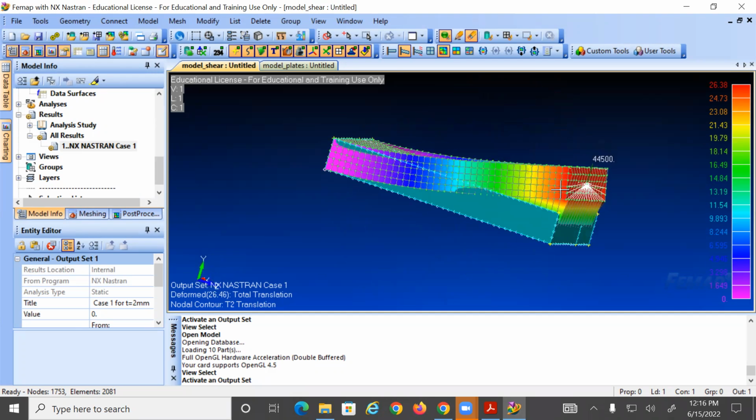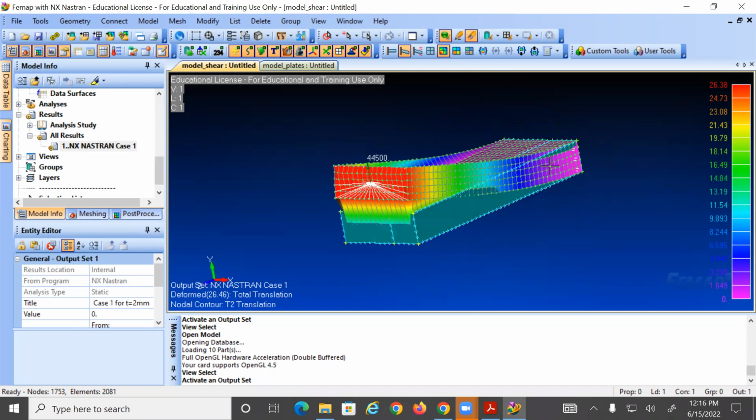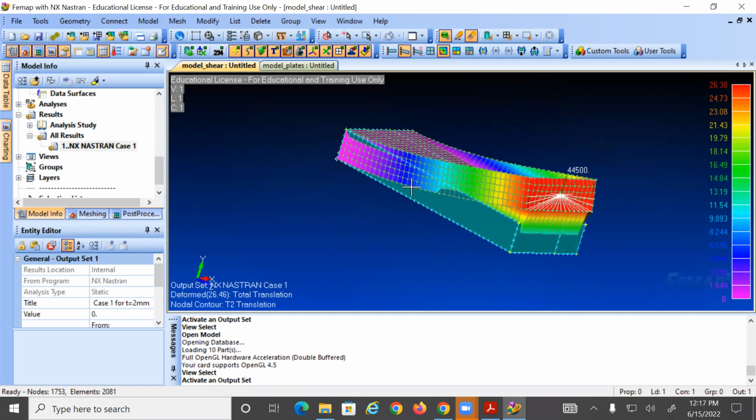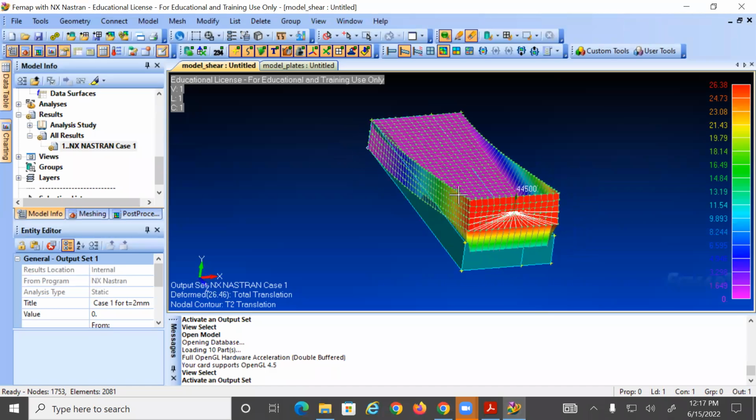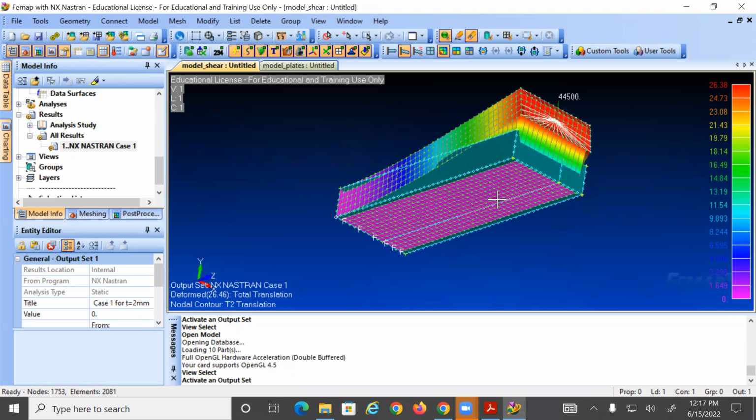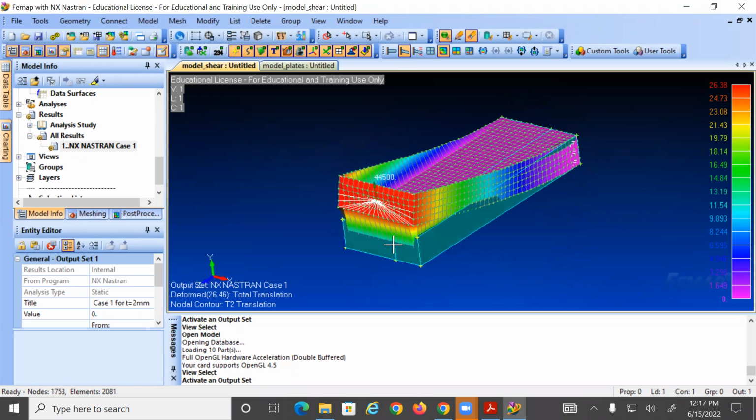That only the panels in the direction of the force will be resisting the load, no? When we do the calculation. And that's exactly what you see over here. Only the panels in the direction of the load are displacing, deforming. The ones at the top and the bottom, they're not doing anything. Okay? So you need to know the limitations when you also do the finite element modeling.